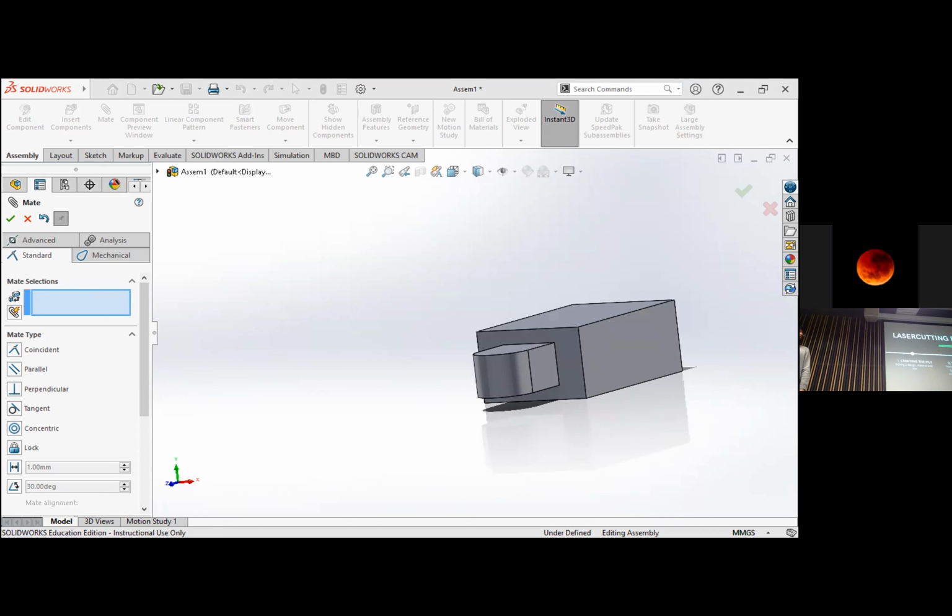So we'll be moving on to laser cutting. So if you want to laser cut your CAD, you basically just create the file. And then there's a few layer types for laser cutting. And then after that, you send your file. You convert your file to the DXF and then add the file to the laser cutter, and then it will just do its job.